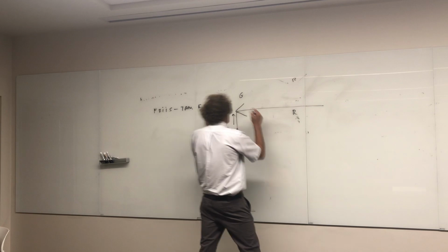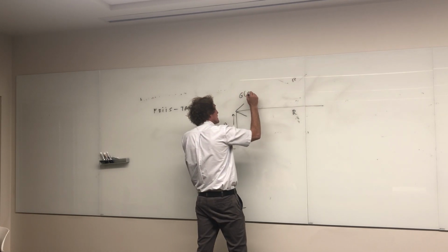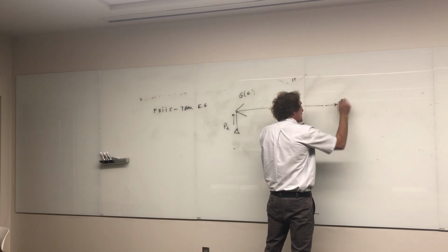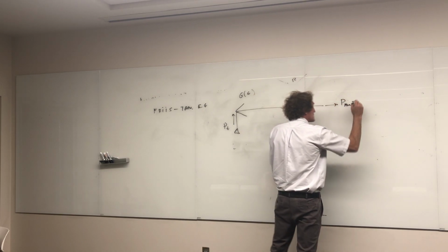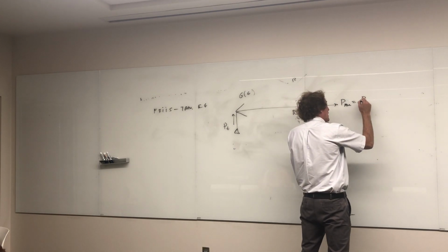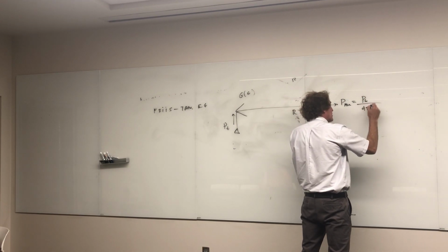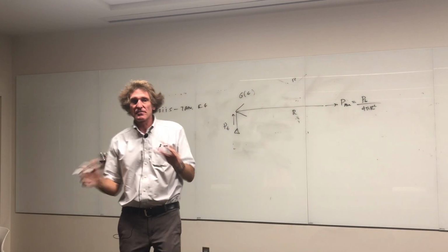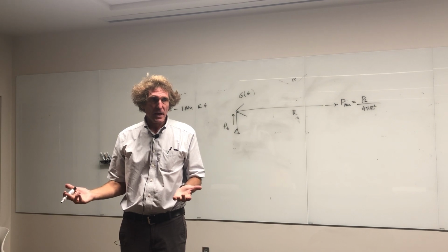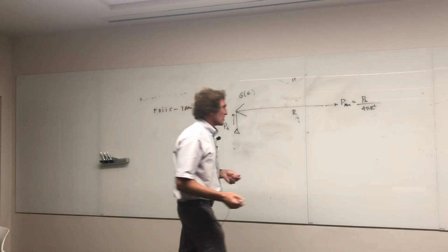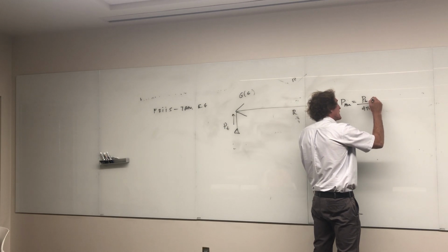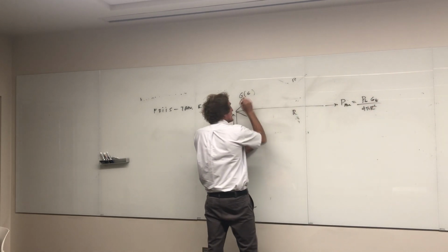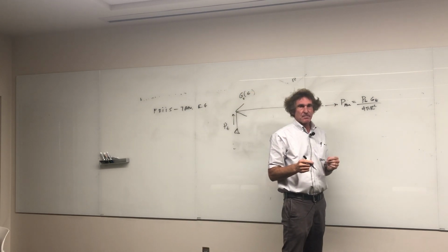now remember that gain can be a function of angle too. All right, we'll just leave it. At distance R away, I can say the actual transmitted power density, that would be PF in watts per meter squared, would be the total power transmitted over 4 pi R squared. Now that's as if the power is just spread out isotropically. Take total power and divide by the surface area of a sphere, right? Then the gain sharpens it. So if I multiply by the gain of the transmitter antenna here, now I know the power density.